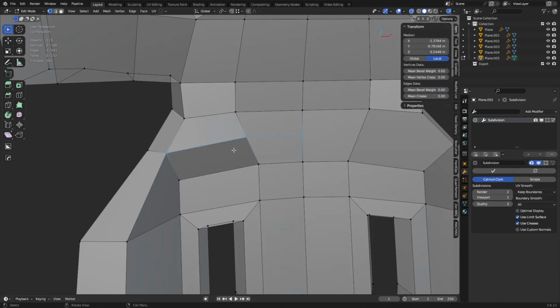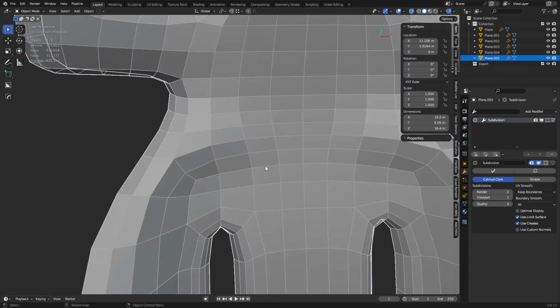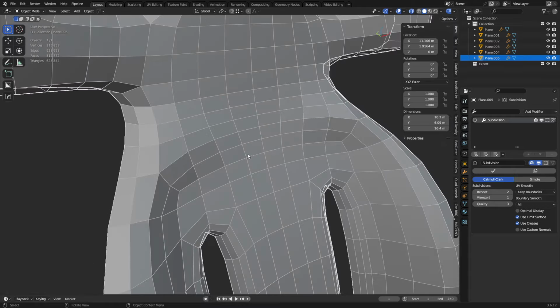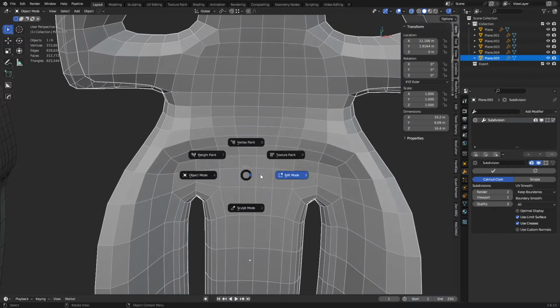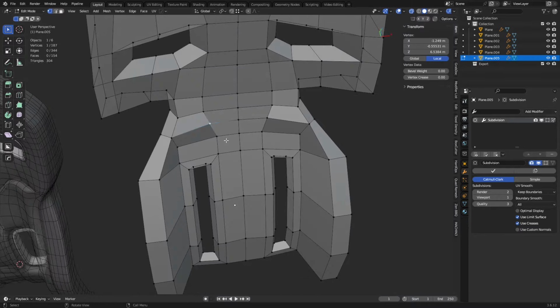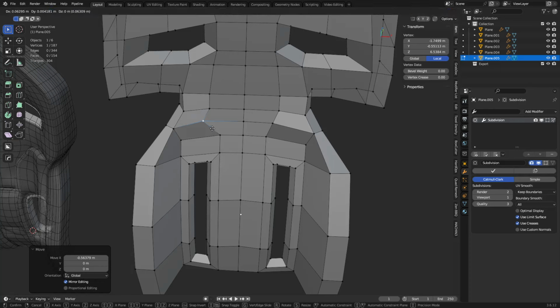You can see, just cutting a big, we had an n-gon. N-gons turn into e poles. Triangles turn into in poles. So when you cut it in half and turn it back into quads, it probably will still have the e-pole. It might just shift the position of it around. So it's little things like that, and that's why I was saying all those things are really your fundamental building blocks. You cannot get away from them really, to some extent.